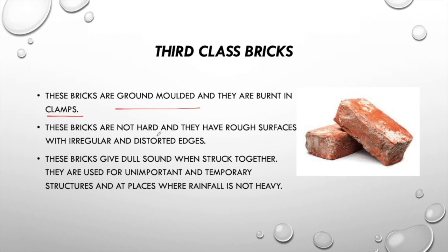These bricks are not hard and they have rough surfaces with irregular and distorted edges. Now these bricks give a dull sound when struck together. In the test of soundness these may fail. They are used for unimportant and temporary structures and at places where rainfall is not heavy.